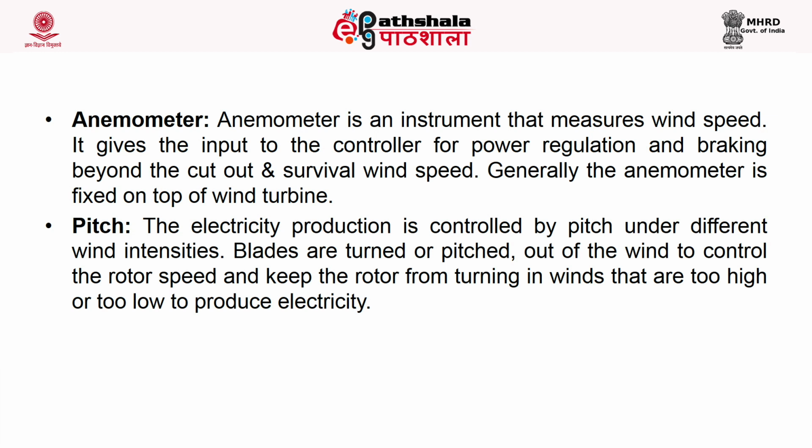Blades are turned or pitched out of the wind to control the rotor speed and keep the rotor from turning in winds that are too high or too low to produce electricity.